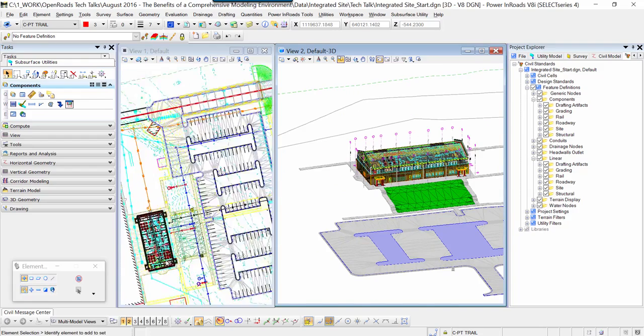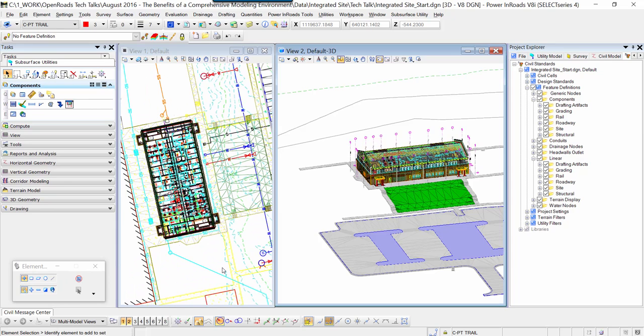Again, everything is based off coordinates. It's based off a coordinate system. To locate that building, you know that a lot of times building designers and architects work in a world of 10,000, 10,000, a world where the state plane coordinate system doesn't exist. So how do we make that transformation from that world to our world of state plane, lat long, real world coordinates?